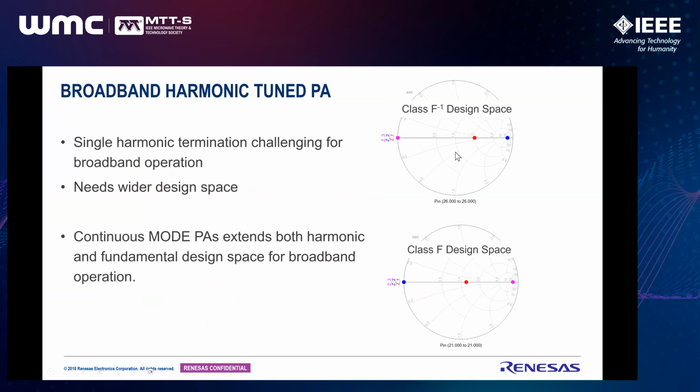But the point is, for a broadband operation, we cannot maintain the second harmonic source termination at a fixed short circuit termination.